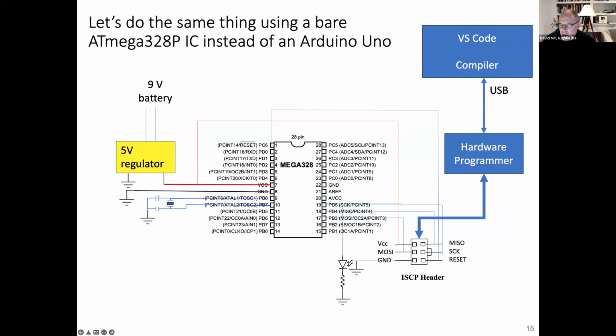Main.elf was the name of what's called the object file. And we're going to go through this in more detail later on. It's not something you have to worry about right now, but it's an intermediate product. After you compile, there's what's called an object file. That object file has to get linked with other object files, and then it has to get turned into a hex file. That's all the internal machinery of the compilation process. And we'll say more about it later on. For now, you don't even have to know about it.